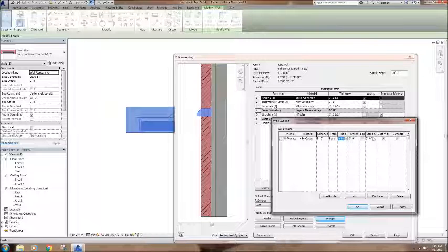I don't want this to be on the inside over here by my chipboard. I can also set this back or offset it. Basically what these do is if I do a 1 inch and then maybe I do this 3 inches, hit apply, so you can see it jumps this direction. And I'll go back to 0 there and go back to the 0 there. Okay, so that pops through there.